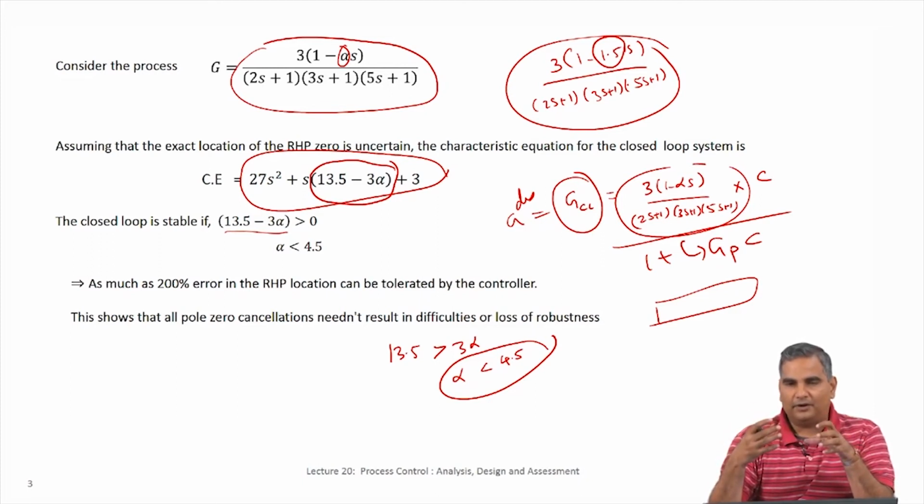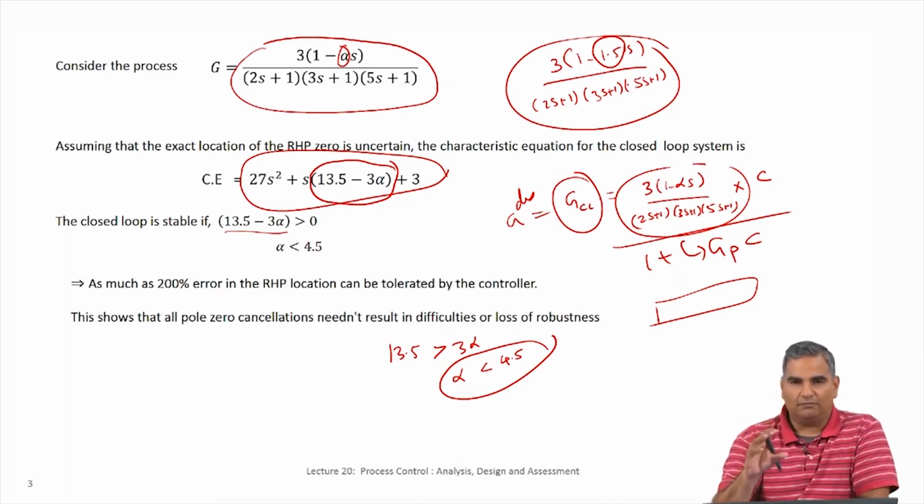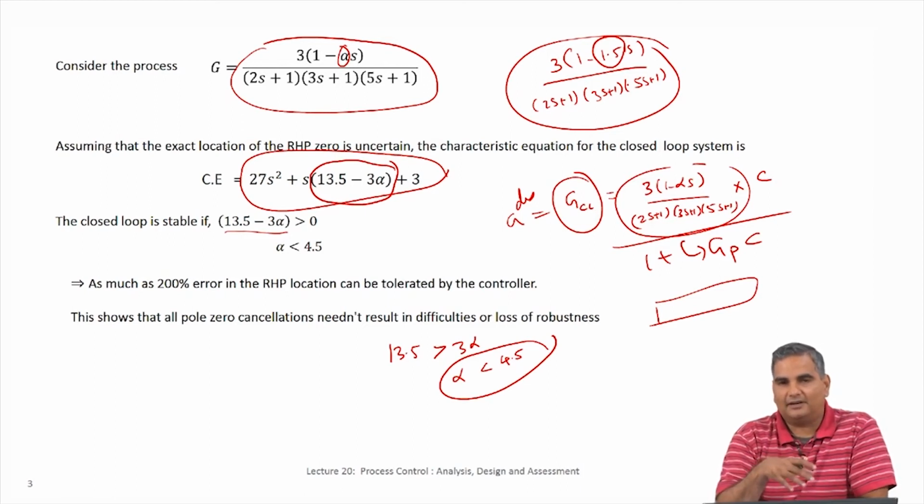The controller design is all based on the notion of a model, but to study the true effect of the controller in the closed loop, you have to use the process transfer function. So, this notion of predicting something with the model, or designing a controller based on a model, is going to be a key idea that takes you from your standard undergrad controller to more sophisticated controllers.